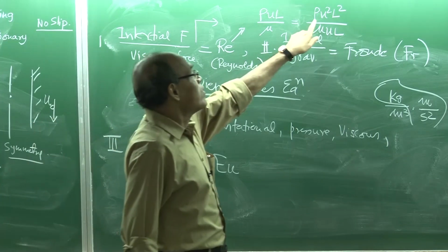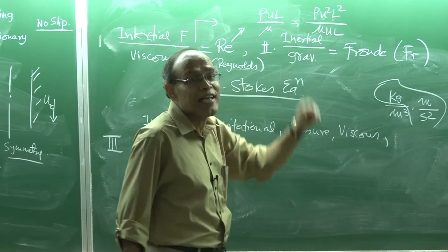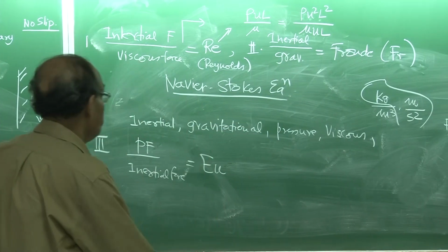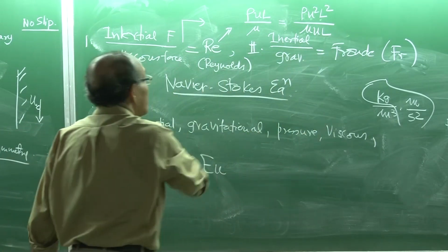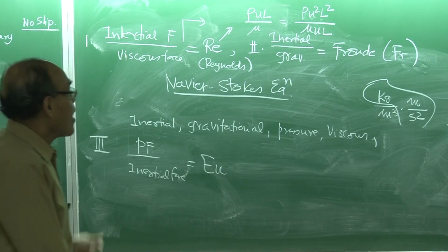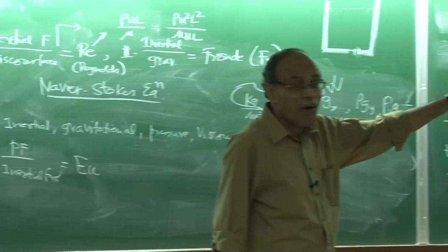Similarly, if you take the unit of rho u square as well as L and substitute it here, this will also come out to be in dyne or Newton, meaning that you are essentially getting a dimensionless number. We also sometimes call it a dimensionless group. So, in fluid flow, the dimensionless groups which are important are Euler number, Reynolds number, Froude number.